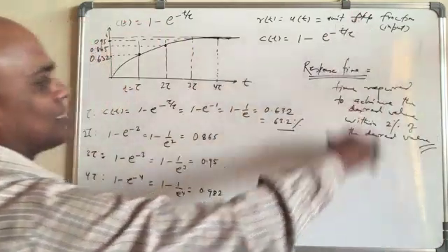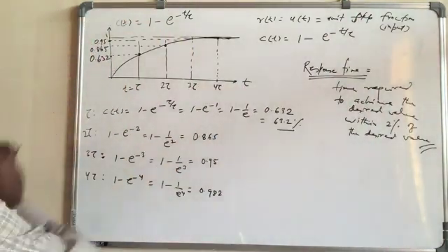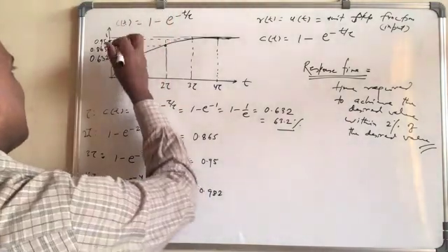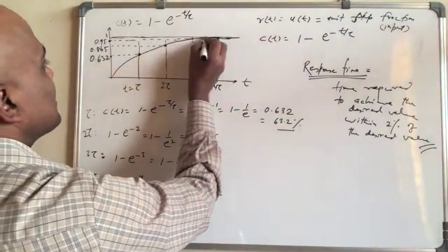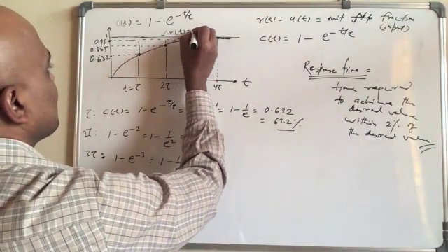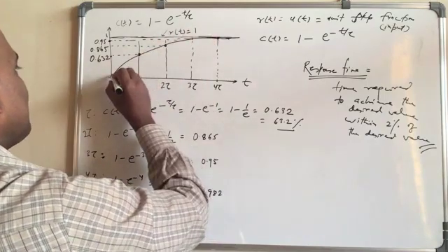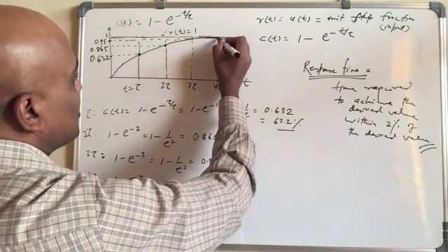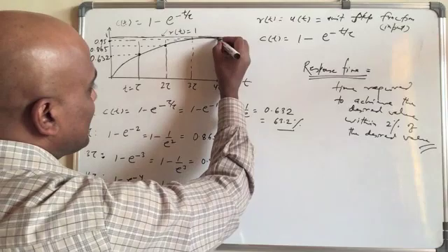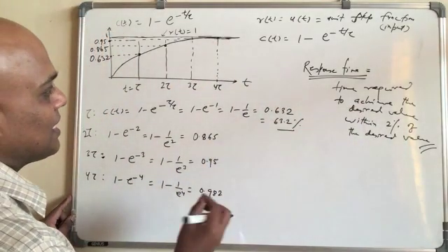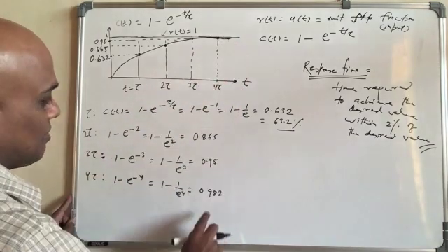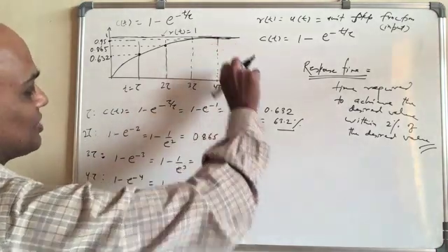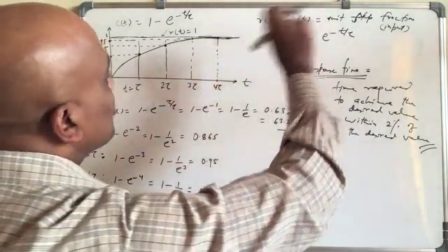So this is my language basically, a simple technical language. What it means is that, let us say you are starting from 0 and you are increasing to 1. You have changed the reference, so r(t) is equal to 1, right? And this is the output, which goes like this. At 4 tau, if you see, it took 4 tau to reach within 2%, because within 2% means 98% or 0.98. So at 4 tau, you will see the value is 0.982, which is within 2%.